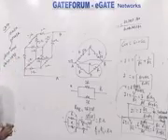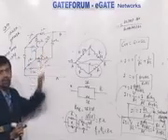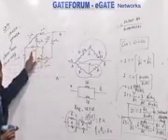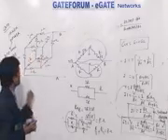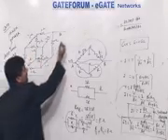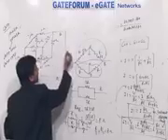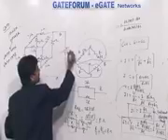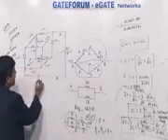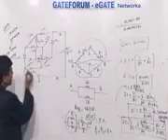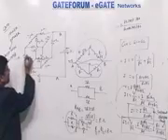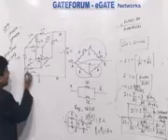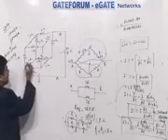Now whenever these resistors of 1 ohm or the same value resistances are connected in a symmetrical structure like a cube, then we need to solve this in a very small amount of time. The same process we can apply, that is, apply voltage, negative positive V. Due to that, current of I ampere will flow. Now this current will be divided into 3 equal branches because all resistors are equal. This is equal to I by 3, I by 3, I by 3.